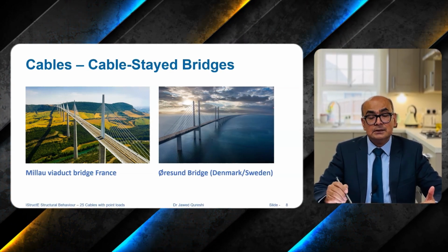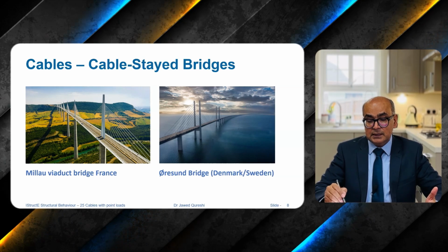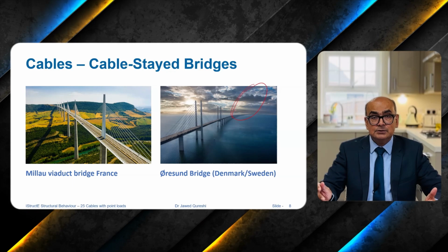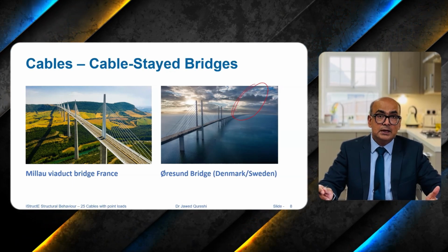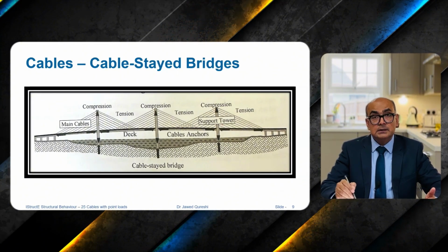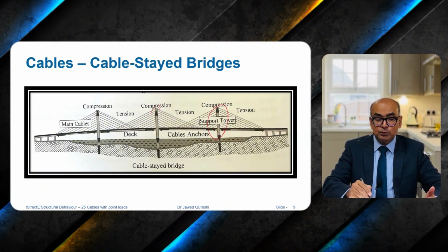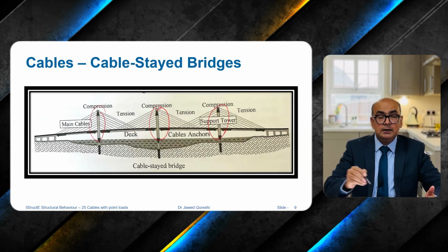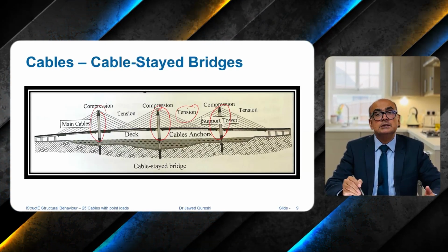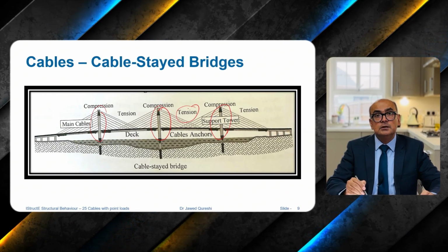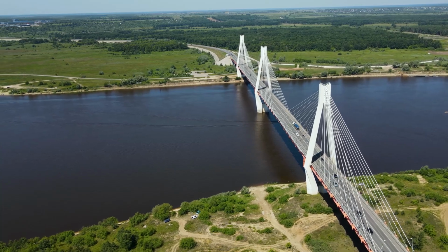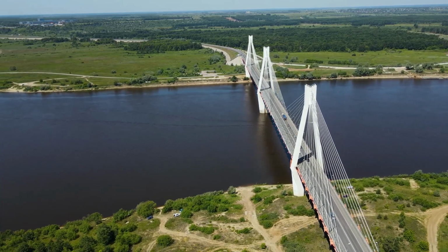This is a kind of hybrid bridge. At the end of the bridge over here, there's a tunnel, so it becomes a tunnel which goes under the sea. This diagram shows cable-stayed bridges. We have main support towers, and they are compression members, and we have cables that take tension. Load of bridge deck is supported by cables, and then it goes to towers.